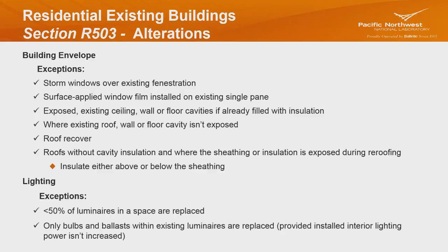Also, if I'm exposing the existing ceiling, wall, or floor cavities during an alteration, as long as I'm filling those cavities completely full with insulation, exempt.